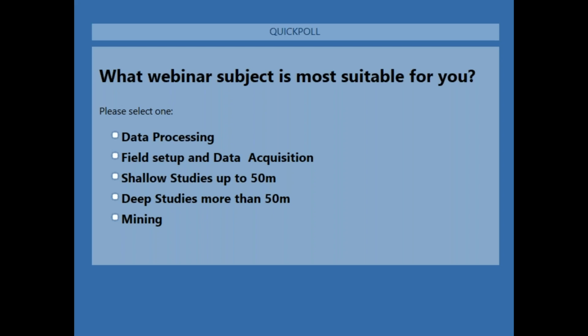Okay, resolution, vertical resolution, horizontal resolution, sample acquisition interval, and electrode separation. Okay, maximum voltage in seawater. Okay, this is another question. I think this is almost the last question. Okay, before the last. The vertical resolution depends on electrode spacing. So the maximum vertical resolution is half of the electrode spacing. So with 1 meter electrode spacing, the maximum resolution will be half a meter.